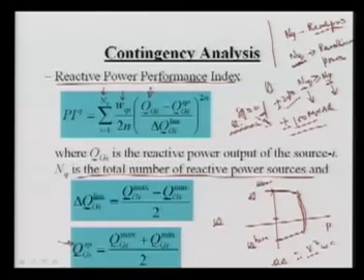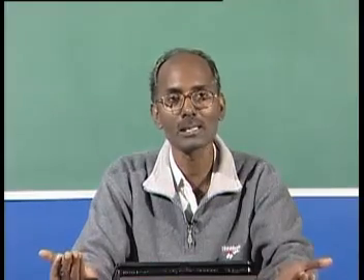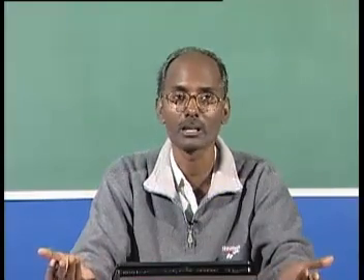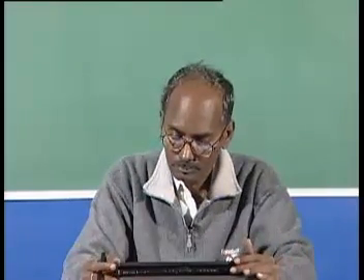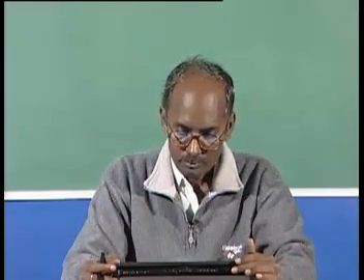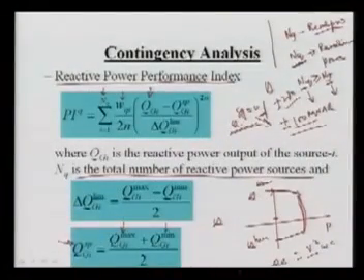Let's suppose it is generating 280 MVAR in the steady state condition. If a fault comes, there will be no margin. It is already hitting the limit, and it has no control during the emergency, because these devices are used for emergency control. So that's why this is the specified value. We are adding the maximum to the minimum value, and taking the average between these two limits.